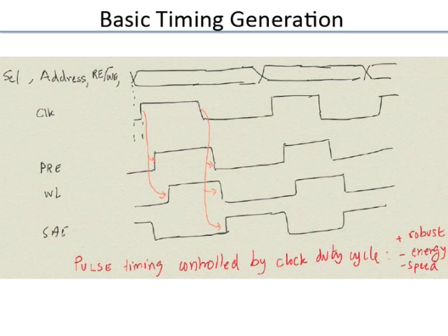You worked hard to set up a small data difference, and then before the sense amp picks it up, you turn on the pre-charge. That is not good. So you want to interlock. So some of these signals you want to ensure this kind of ordering. Pre-charge is released, then you turn on word line, then sense amp enable goes high, and then pre-charge comes down.